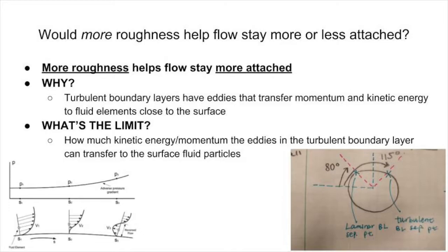As this flow moves along the surface, the adverse pressure gradient is taking energy and momentum out of it until the pressure gradient finally wins and the flow begins to travel upstream. When these fluid particles collide with those coming downstream, the flow has nowhere to go but up and away from the surface. So these are the mechanics of flow separation, collision of fluid particles going both ways until it's forced up and away from the surface.